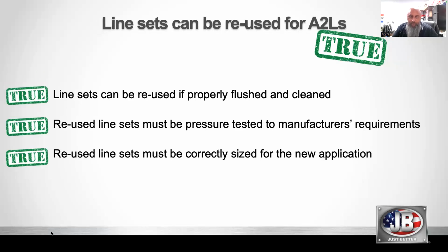Line sets, another one that people are talking about. Hey, am I going to have to change out my line sets? No. I mean, as long as the line sets are correctly sized and they're pressure tested and they're properly flushed and cleaned and purged, you can use existing line sets. And I suppose that's a major thing for most people out there.